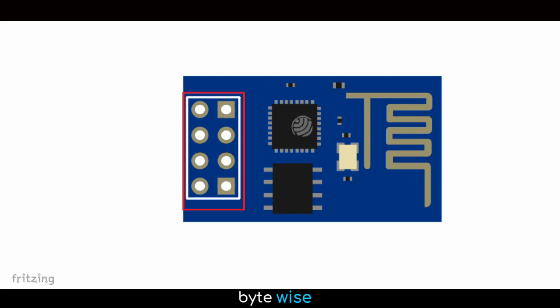Let's take a quick tour. These are the 8 pins that we'll use to connect the device. This is the ESP8266 processor. This is the 512K flash RAM. This is the timing crystal. The remaining components are the LEDs and the resistors that support them.